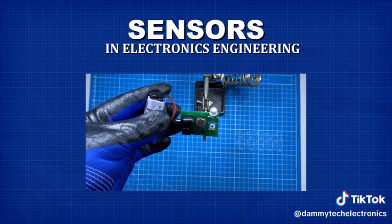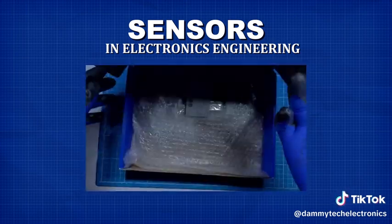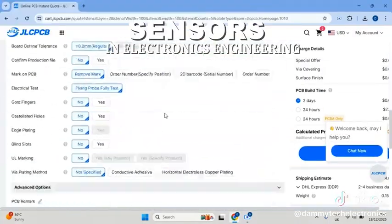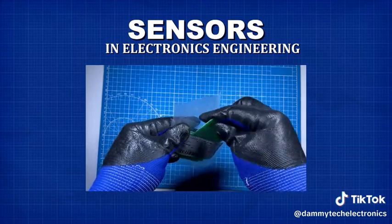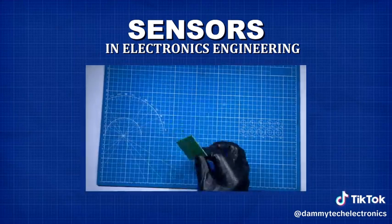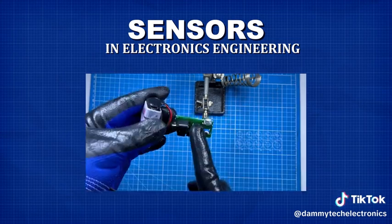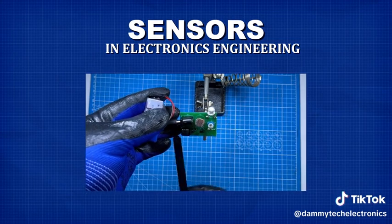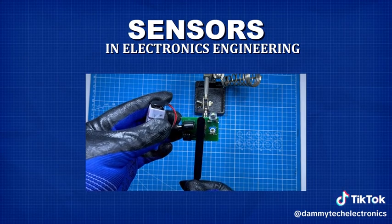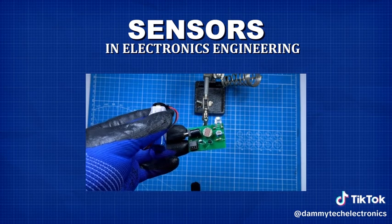For the PCB, I used JLC PCB. After generating the Gerber file, I uploaded it to JLC PCB, selected the board settings, and placed the order. The PCB came out clean, with neat tracks and accurate solder holes. Now after placing and soldering the components on the PCB, let's test the circuit. When light falls on the LDR, the lamp stays off. But immediately I block the light and make the environment dark. The lamp turns on automatically, and that is how an automatic darkness sensor circuit works.